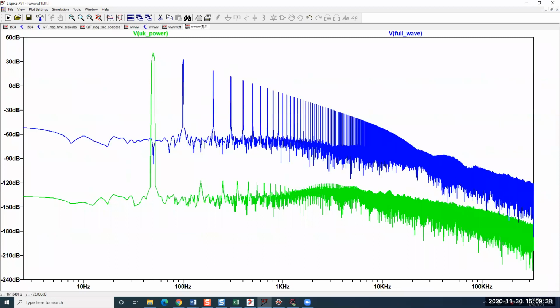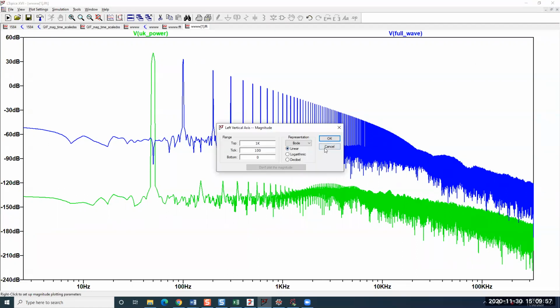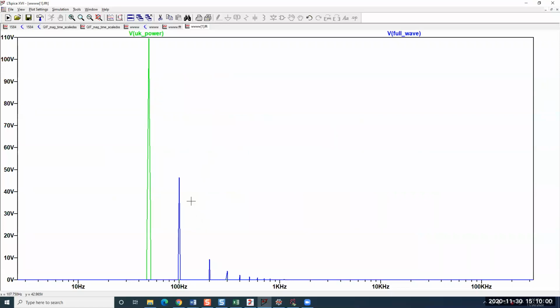Okay. Now, yes, there's more noise, and that noise, well, actually, the absolute value does have higher harmonics, and so that energy is going into these higher harmonics. So you can see 1, 2, 3, 4, 5, 6, almost 7. And so that energy gets pushed out, but also there's a DC offset where that energy went as well, but LTspice doesn't show you the DC offset.